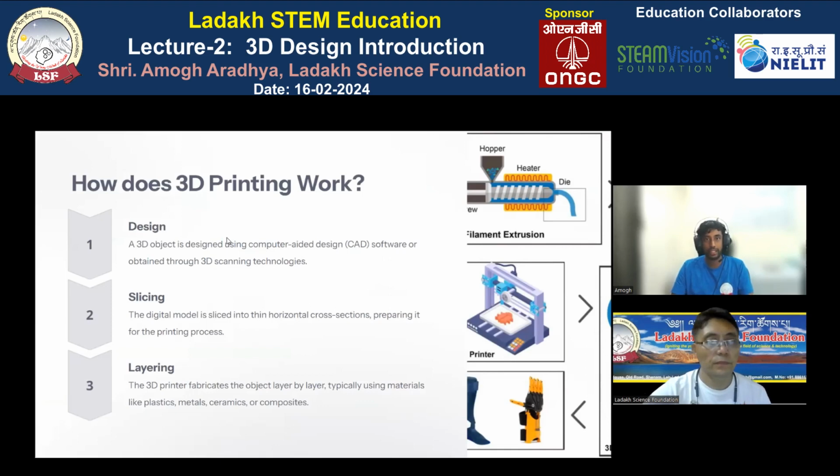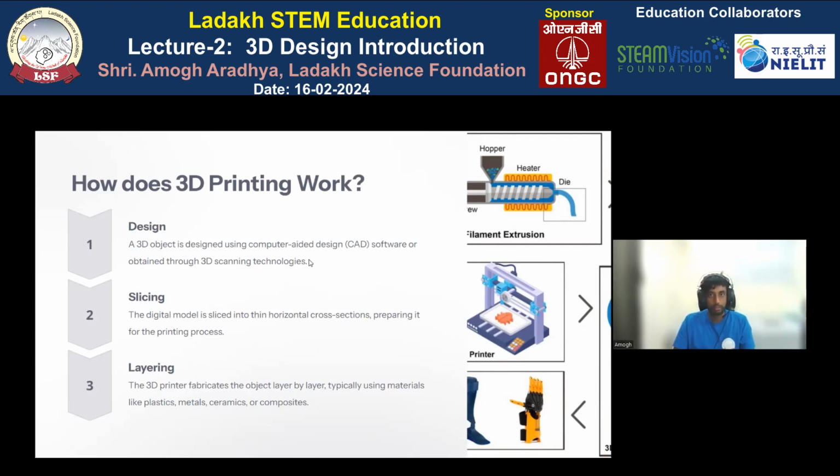Examples are Tinkercad, Fusion 360, Solid Edge, SolidWorks. What you do there is you come up with an idea and model the 3D printed part. You start off with geometric designing by measuring the item or coming up with an idea, and then slowly start forming it into a 3D model.